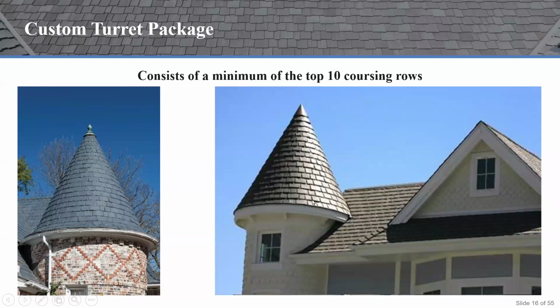If you can get that information, then there are manufacturers that will calculate that turret kit for the contractor and then bundle it by row to make it as easy as possible for them to install it out in the field. So I highly recommend taking a look at turret kits if you are specifying or working on any projects that involve radius features like you see here.